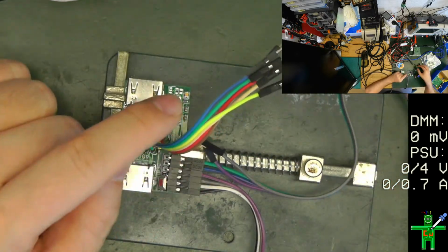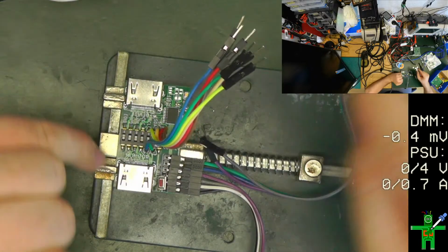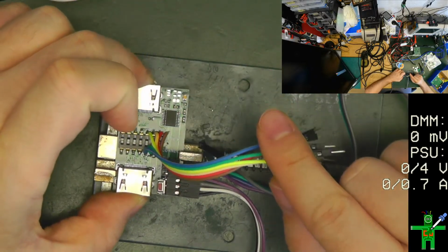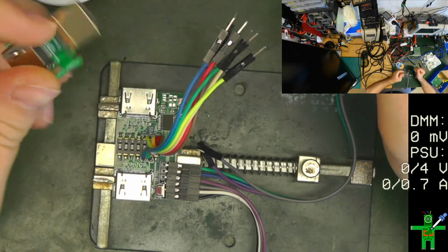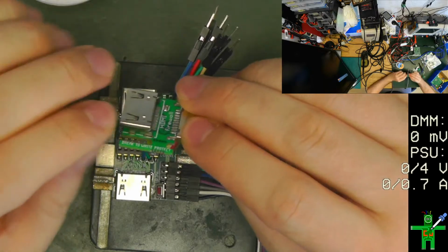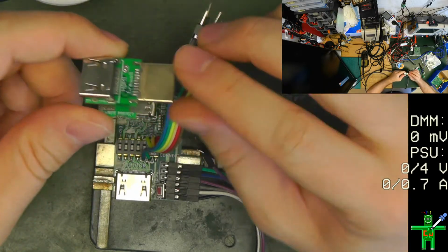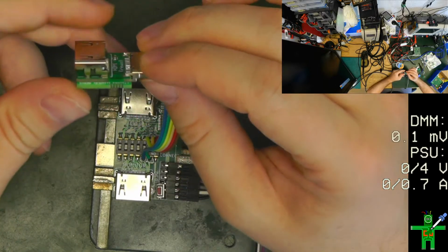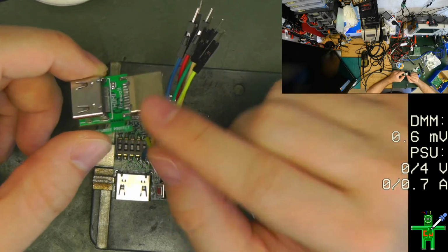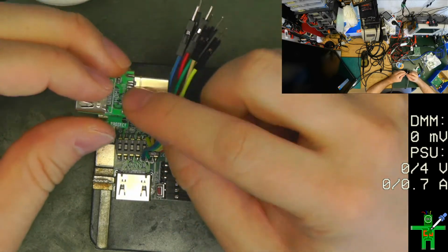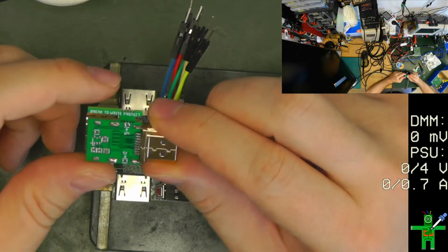So it doesn't have this plug and receptacle format anymore. On one side, you have 2 times the receptacle. This one was useful because you just plugged it in the back of the screen, and then you just need one cable, and it's quite a nice design. The problem is that there is an edge connector which is not easy to solder because you have to solder on both sides. So this is hand soldering plus hand placement, and this is always hard for manufacturing.